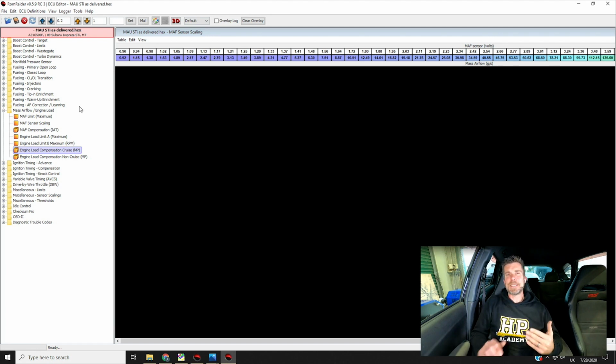But the other aspect, and again this is without trying to derail the webinar, this is quite unique to Subaru. There are some mechanical issues with the factory fuel system design that create a little bit of weirdness in terms of high frequency fuel pressure oscillations. These are quite prominent around 2800 to about 3400 RPM, and they can play havoc with the fueling. Essentially it causes harmonics based on the frequency that the injectors are opening and closing, and this causes pulsations in the fuel pressure, which means that when the injector opens, sometimes it's delivering less fuel than it should be because the pressure at the injector becomes lower. Alternatively, sometimes it will inject more.